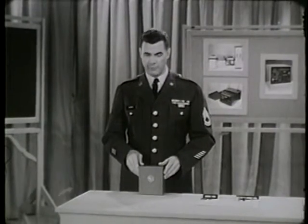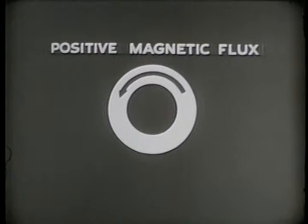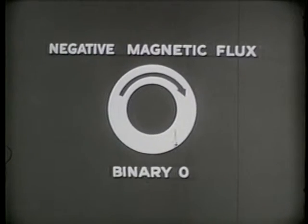Why do we use binary? Because a bit can be represented by any bistable device, and a magnetic core is a bistable device. Bistable, because it can be magnetized in two directions. When the magnetic lines of force point in one direction around the core, they are a positive magnetic flux, and the core is said to hold a binary 1. If the direction of magnetism is reversed, the flux becomes negative, and the core holds a binary 0.